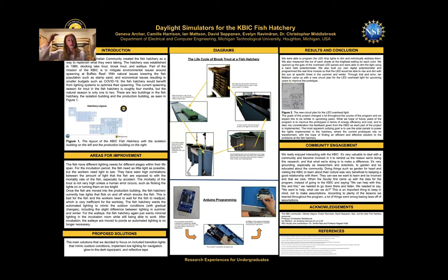For the overhead LED lights, the big panels that we're planning to put into the production building, we went through a large process of trial and error and finally are on a good path, or so far we think. We were able to get them to dim using a handheld potentiometer. And from there, we built our own digital potentiometer through a series of resistors and adding in transistors.